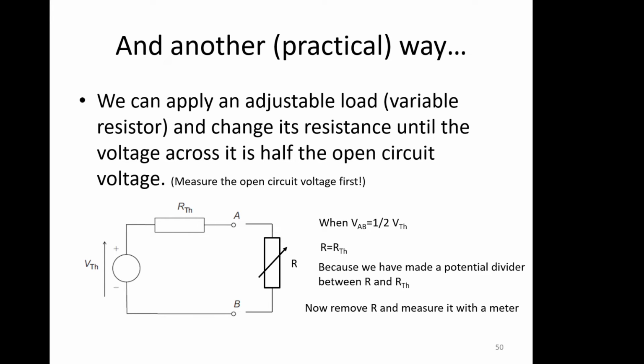Yeah, okay, it simplifies the resistor being a complex component. And that's all you've got to do: replace R with Z. And there you go. What you get is a short circuit current at AC. So it only operates at certain frequencies. You've got to model this at a fixed frequency if you've got other components like capacitors and inductors in there.